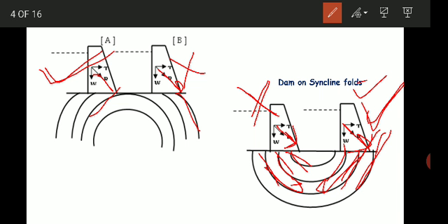So there will be a seepage through porous rock to the reservoir basin only. So the dam which is resting on the upstream side, where R remains parallel to the bedding plane, can cause a leakage. So if there are folded rocks, they are not only under strain but they are also physically fractured along the crest of the fold.